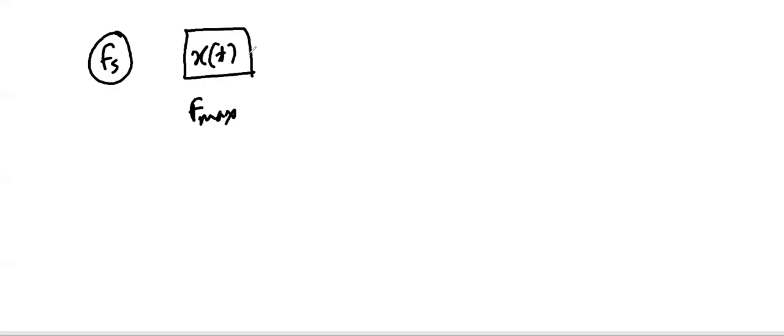For example, if x(t) is a voice signal, we know that it is mostly from very close to 0 to 20 kilohertz. So this is the audible range, the voice signal. However, we also know that most of the energy of our voice signal is between 0 to 4 kilohertz. So it is obvious that we can cut down the higher frequency components.